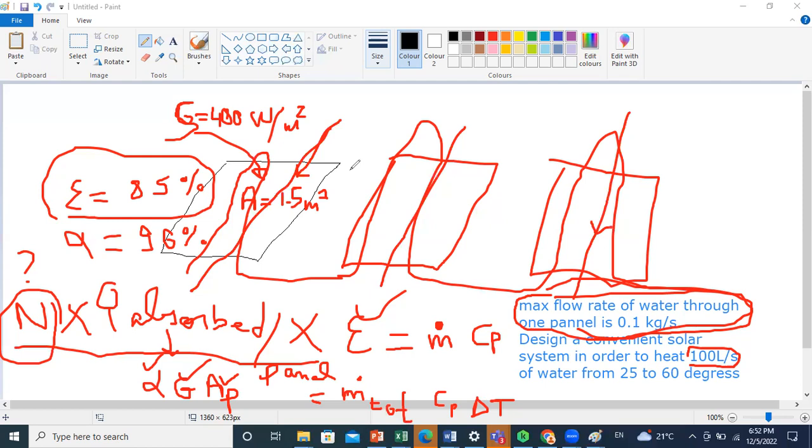Okay, so these issues of how to do it will depend on the practicality of the design. When you perform any design, you have some preliminary engineering calculations that you are doing now. But after, if you want to decide whether to pass the whole flow rate at once or divide it into parts, you should then study the head losses, etc. This will be much more complex.